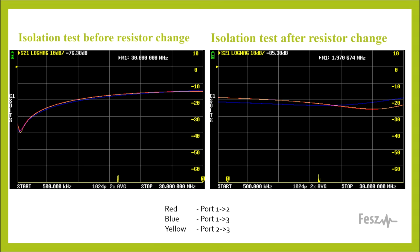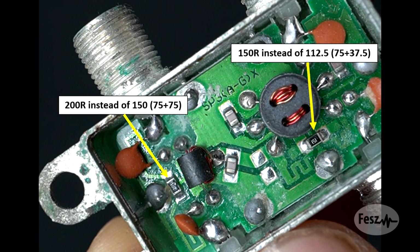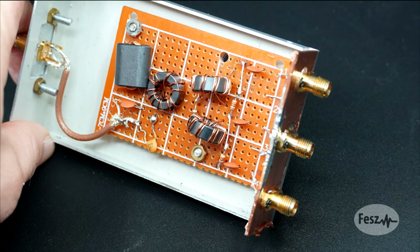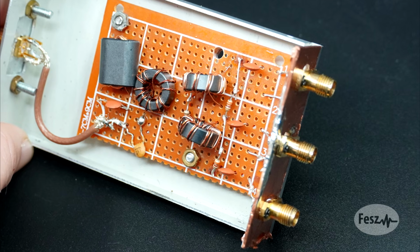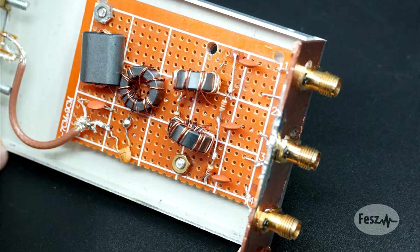So after changing the isolation resistors and remeasuring, similar to what the simulator predicted, the overall results did become a bit more uniform. The minimum dip has disappeared, but the attenuation improved in the higher frequency range. I guess this is why in commercial splitters, the resistor values are higher than what you would expect them to be. For this circuit, these are still not the optimal resistor values, but rather something in between these and the ideal ones is what's probably necessary.